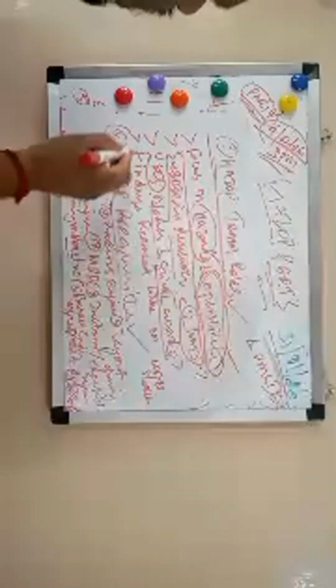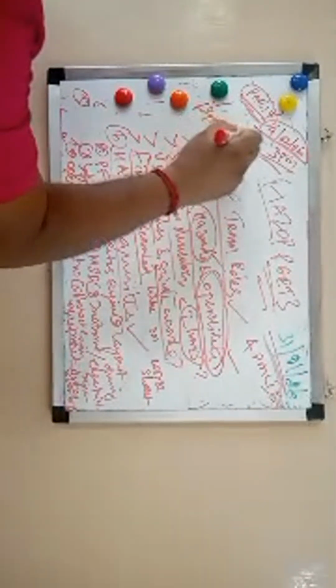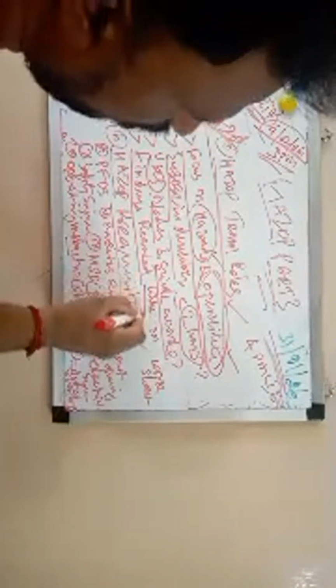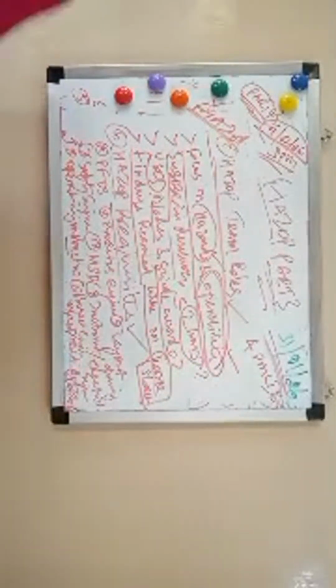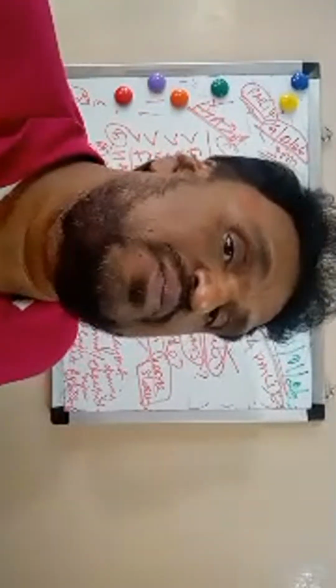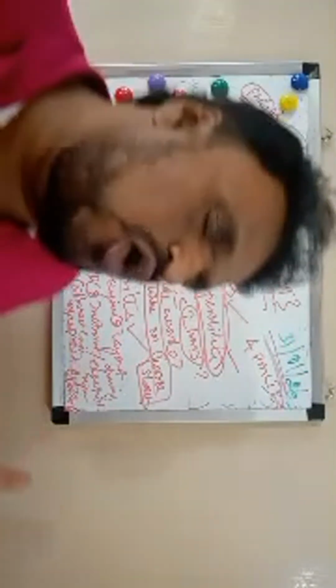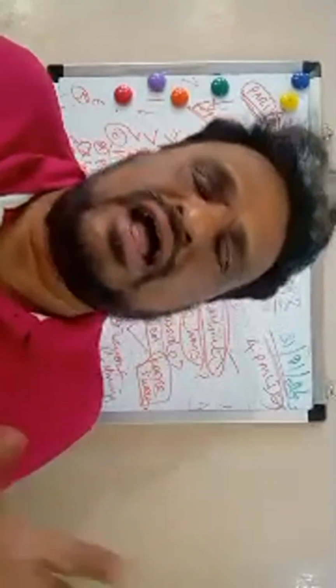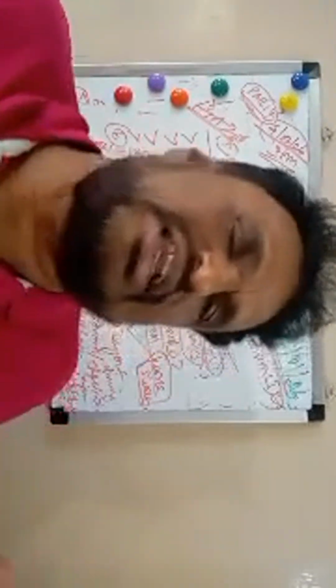Then you have findings and records. Whatever you are doing in the HAZOP, you have to make it live on worksheets. You have to record it on worksheets. That's very important. So this is the team. As I said, who is the team? The project engineer is the team leader, and the electrical engineer, safety engineer, operation and maintenance specialist.